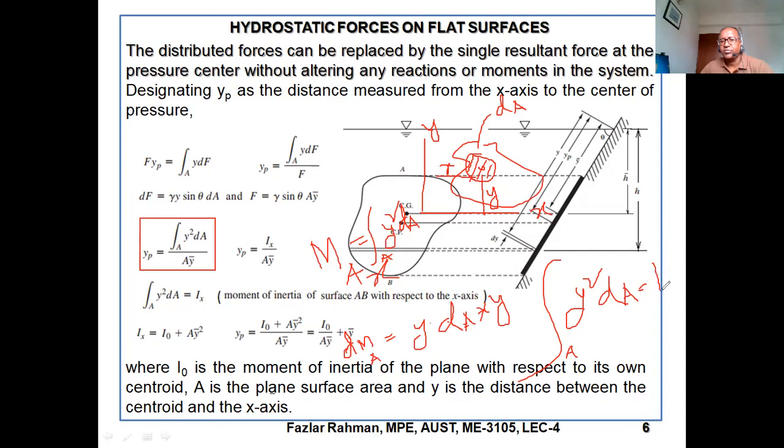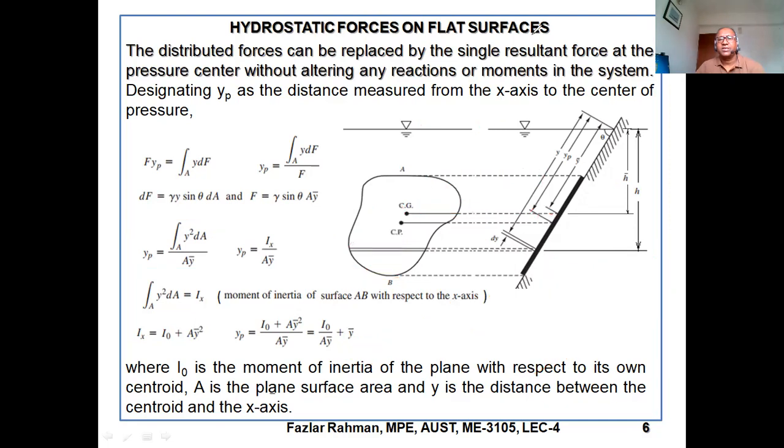That means ultimately you are getting moment of inertia along the x-axis, because the distance from the x-axis is y. If you take this distance x, then it will be about the y-axis. Okay, so Ix. Did you remember this equation? Anyone? In engineering mechanics, you look in your class notes that Ixx equals integration of y square dA, and Iyy equals integration of x square dA.